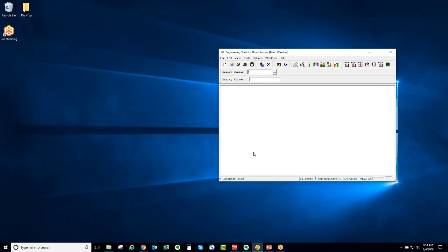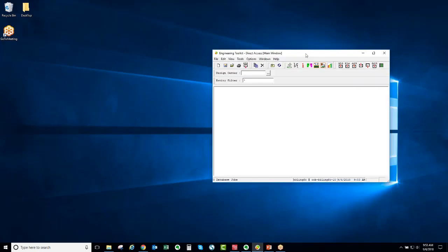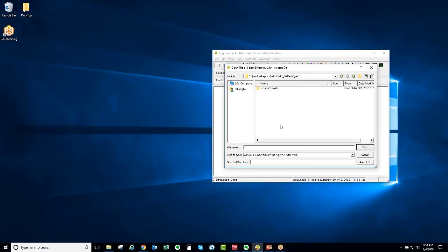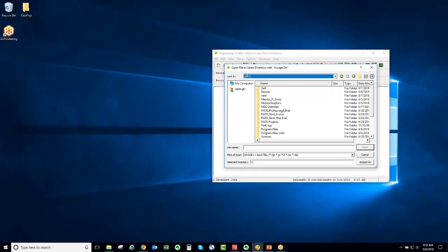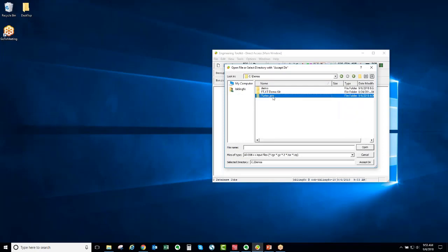So what I can do is if I output ODB++ data from my CAD tool, which every major CAD tool in the industry can output, I can open that data directly in Valor. We do have the capability of bringing in actual Gerber data, of course. We also have some EDA interfaces for bringing in native CAD data as well. But how do I go ahead and get started here? So I'm going to just click the open button and go out and find a design where I've output Gerber data for it. So let's go to my demos here and I'll go into this design.